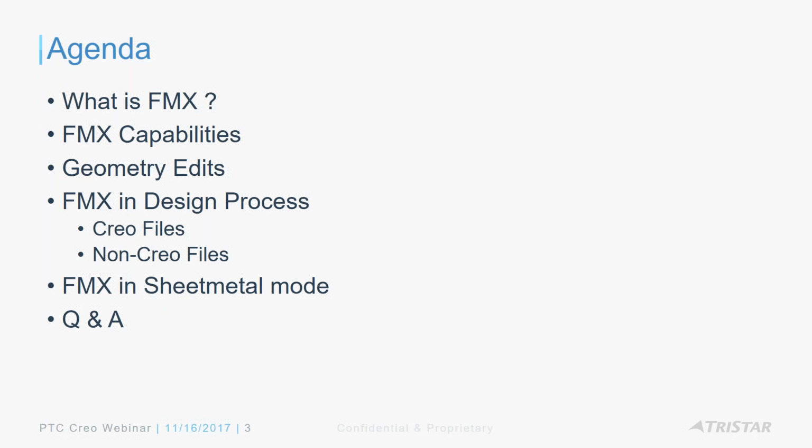So we'll just go through a few use cases where you might be able to benefit from the geometry edits inside of FMX. Starting Creo 4, FMX is also supported in the Sheetmetal mode. So if you get any Sheetmetal parts that were done in a totally different CAD system, or even if it's a step or an IGES, you are able to essentially featureize it inside of Creo Parametric.